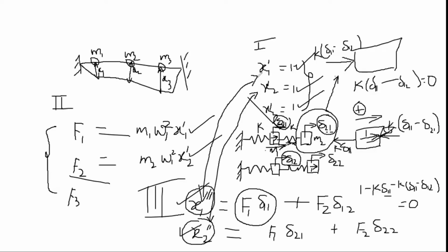Okay, now we'll again match these values with the previous ones. If these are matching, then we'll equate and calculate the value of omega square. If they are not matching, then we'll start with these values as the assumed values, calculate the inertial forces because of the new values, and then calculate the next new values here. Okay, and then again start matching.